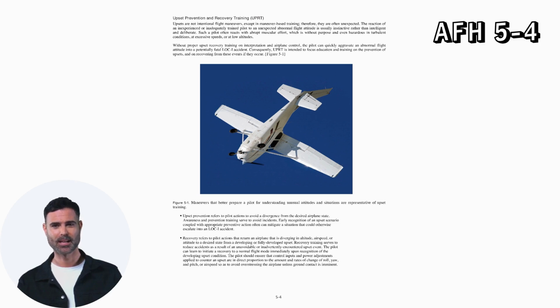The reaction of an inexperienced or inadequately trained pilot to an unexpected abnormal flight attitude is usually instinctive rather than intelligent and deliberate. Such a pilot often reacts with abrupt muscular effort, which is without purpose and even hazardous in turbulent conditions, at excessive speeds, or at low altitudes. Without proper upset recovery training on interpretation and airplane control, the pilot can quickly aggravate an abnormal flight attitude into a potentially fatal LOC-I accident.